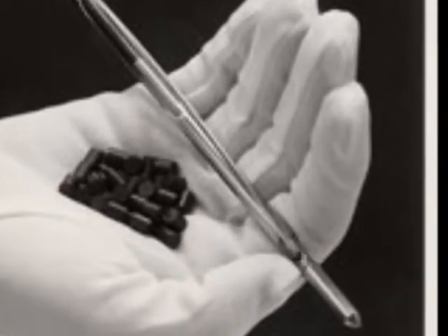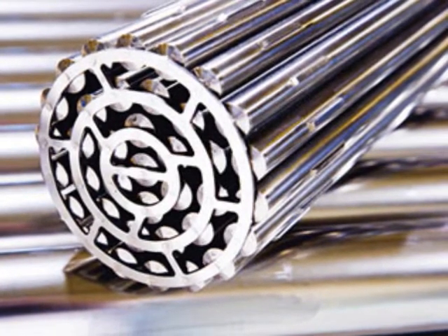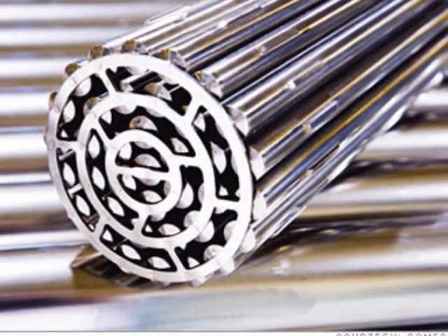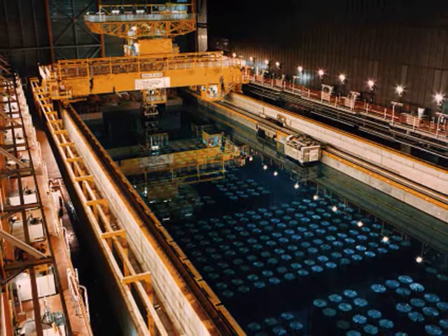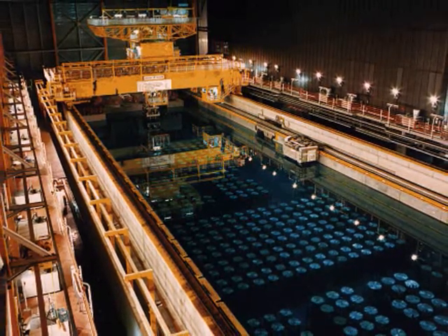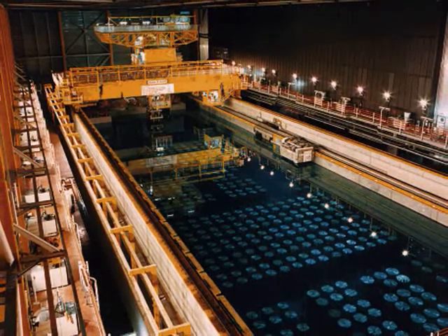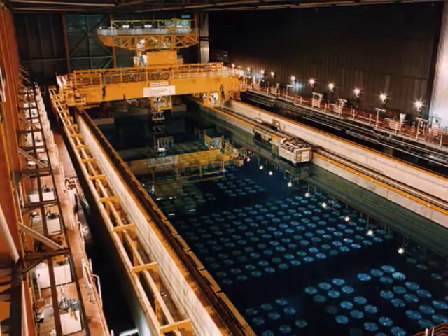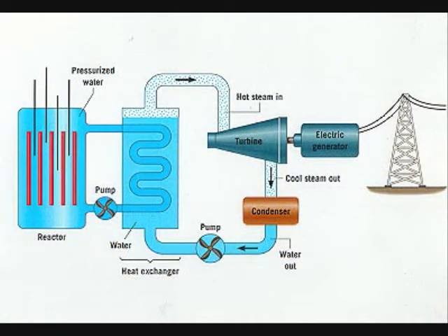That rod is then put together with a bunch of other small rods, and then this produces what we call the uranium rods, which are actually a series of much smaller rods. So these nuclear fuel rods are then stored in tanks of water because they are literally warm to the touch, not because of the fission, but because it's a radioactive substance, and radioactive substances give off decay particles, and those decay particles cause the materials surrounding them to heat up. And essentially the nuclear power works in a similar sense to the way that we use when we burn fuels, and that is that the reactor core becomes very hot, it heats up water.